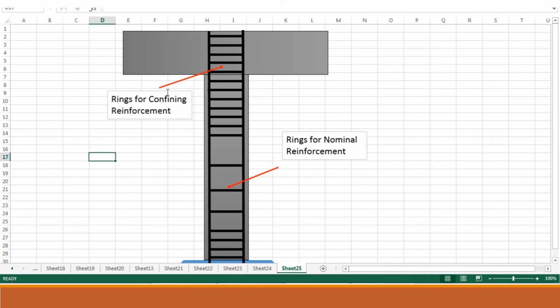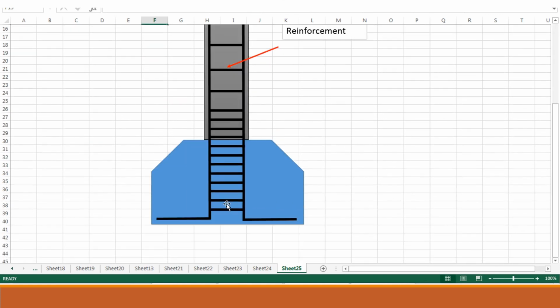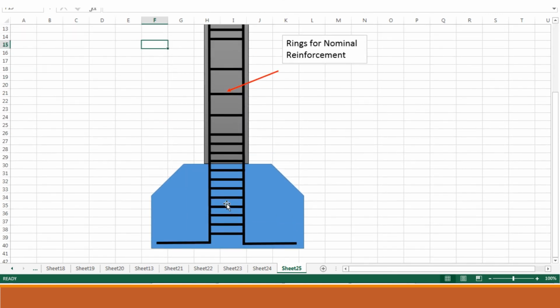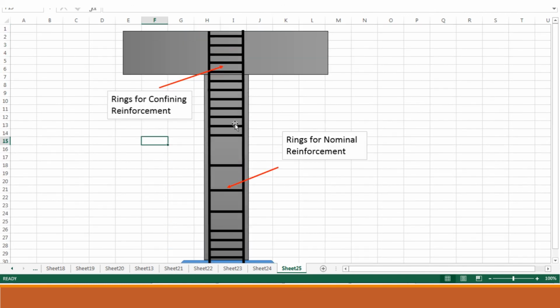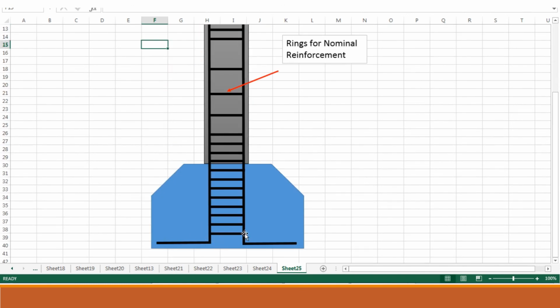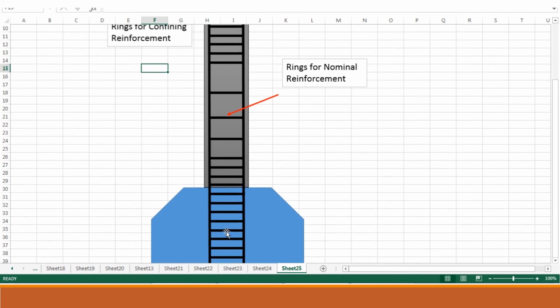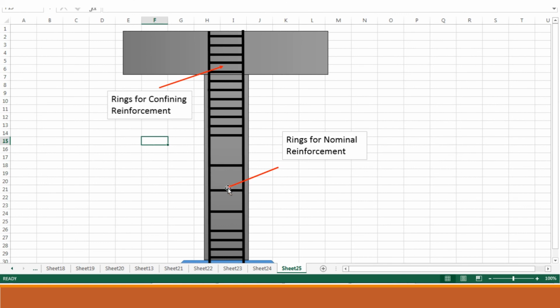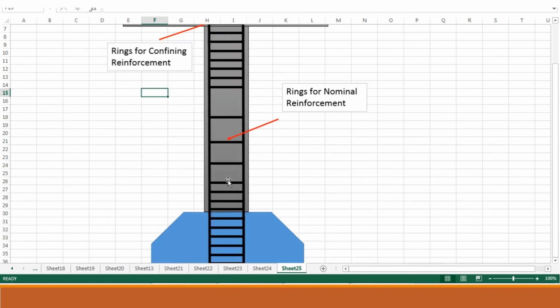Now this is a beam at the top. The column is running throughout, it's a continuous column, and at the bottom it's fixed with the footing being provided. So the column longitudinal reinforcement is running right into the footing, and then we have a development length here. But what we also have is that in the middle portion, apart from L0 from the face of this, L0 is the distance, the face from here.